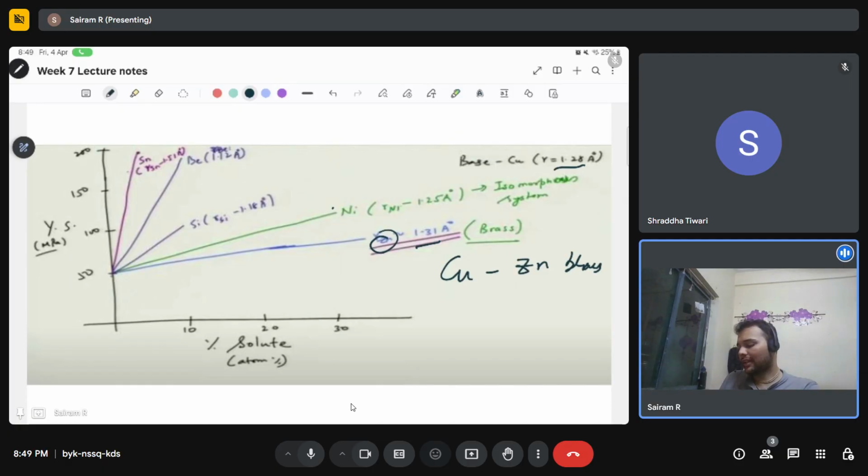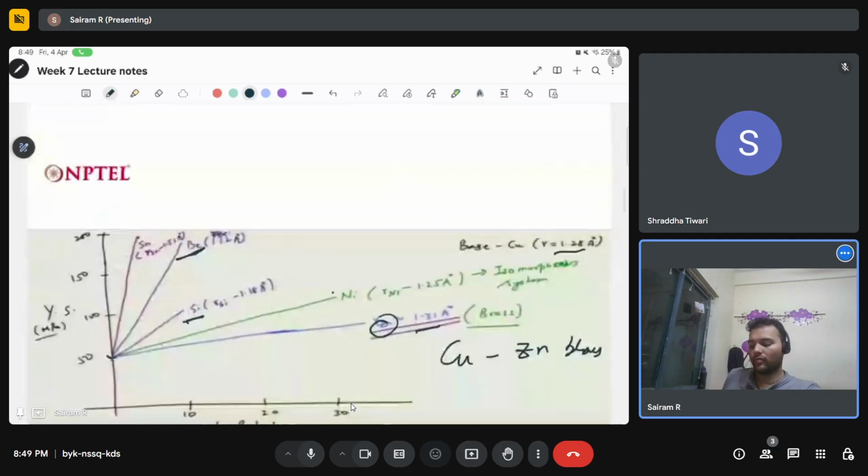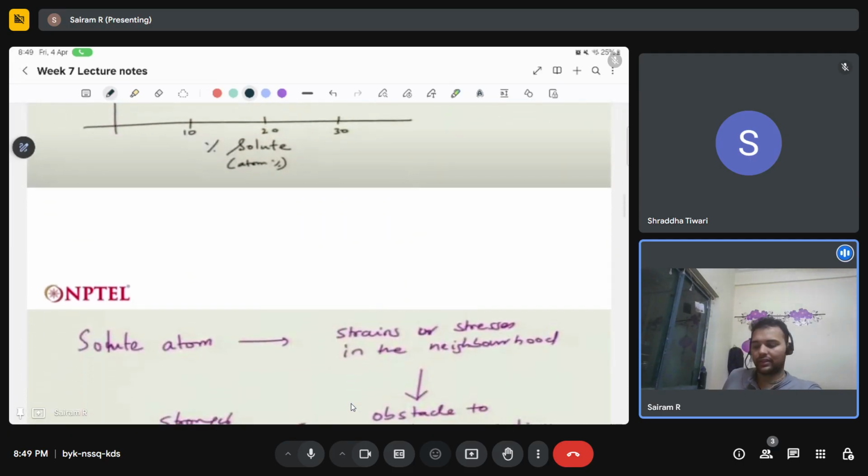However, in the case of say copper tin or copper beryllium or even copper silicon, substitutions lesser than 5%, lesser than 10% is sufficient to be able to increase my yield strength from say 50 MPa all the way to 200 MPa. And this is purely from what we have discussed above, right?